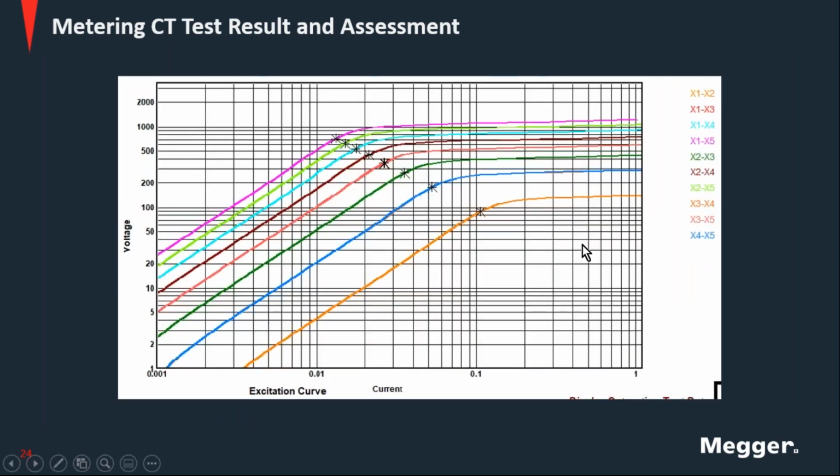Well, what the security factor tells you is, for a particular overload, say 10 times, 20 times, or 5 times the nominal current of the CT on the secondary, what is the cutoff point that you want on the error? And the error on the CT, as Volney showed, is the excitation current.